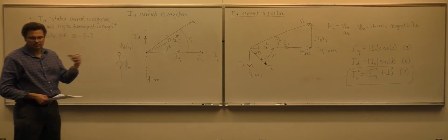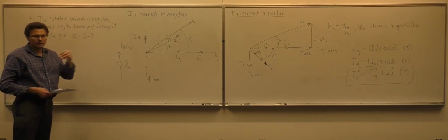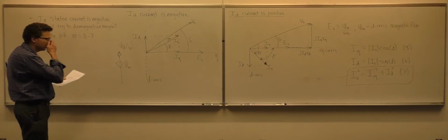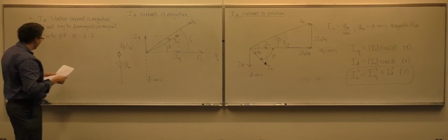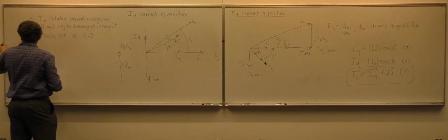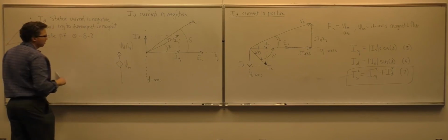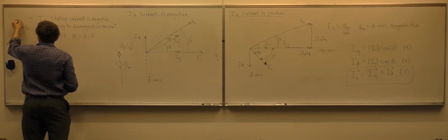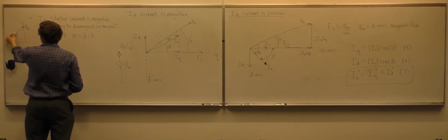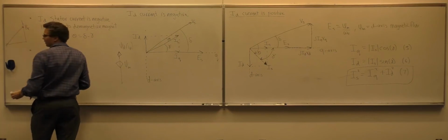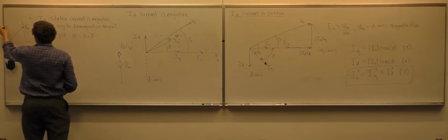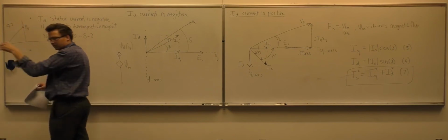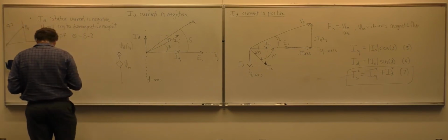We're actually increasing the effective rotor field. You could actually get to the point where, on the magnetization curve, if you apply it enough, you could shift the magnet operating point into the first quadrant. This is the second quadrant. You could go above BR even, because you're adding flux.